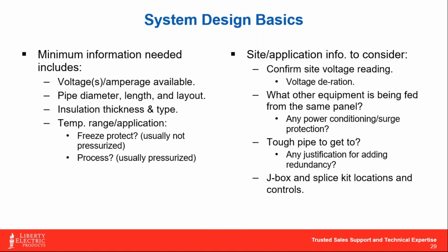It's a great justification to think about having a primary heat trace line that is connected to power that would function and do exactly what its intent was, but to also have a secondary line installed and then insulated over. We can leave those two cut pieces of cable at the end with end seals on them to protect them from moisture and, over time, damage or ingress, so that when the first cable eventually dies, let's say in 15 years, you can literally just hook up the new cable and you're back in business for another 15.